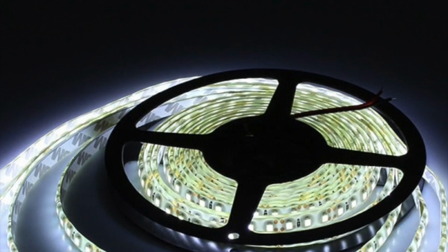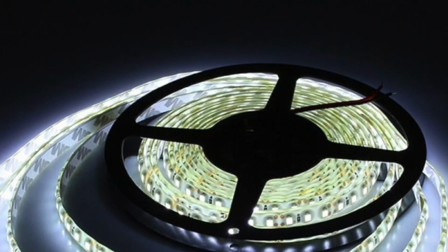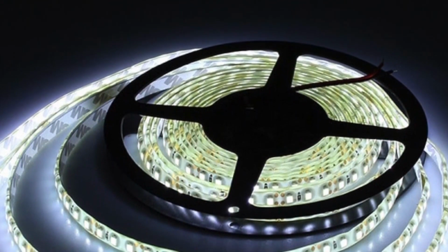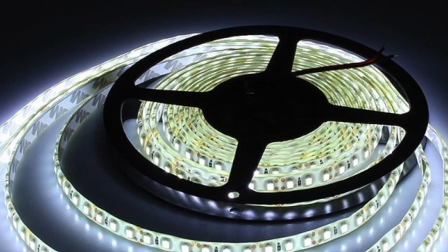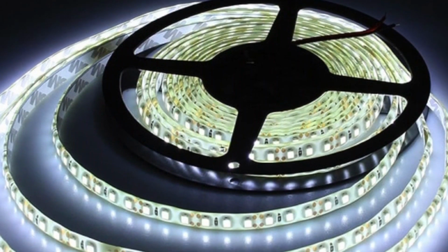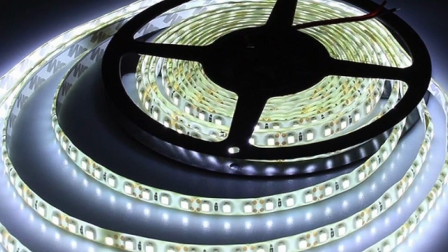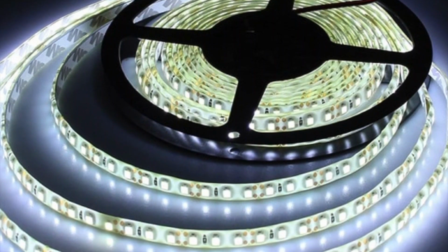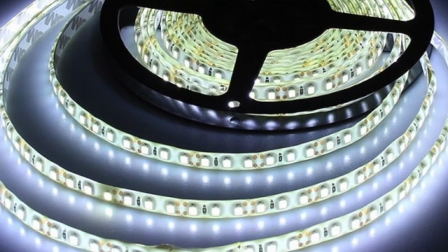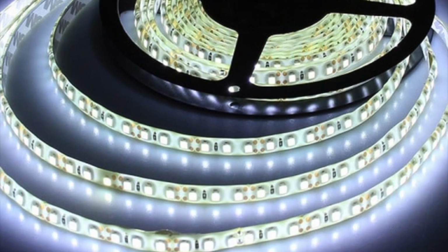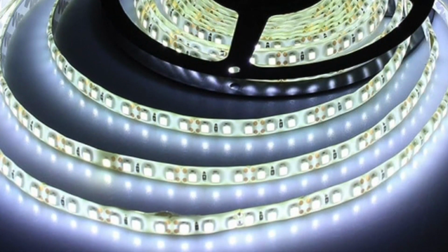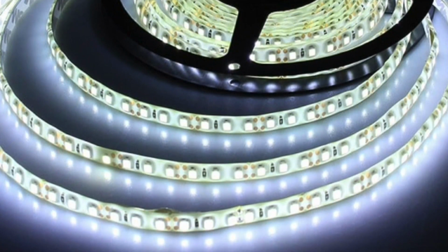However, it's safe to slightly over-amp your projects. Since amps represent the potential rate of flow, not absolute magnitude. Choosing a power supply that provides about 20% more than the max amperage you plan to use will help decrease heat at the power supply and support the longevity of your lights. It's a good idea to do the math to ensure that your power supply provides enough amps to light your lights at full white, too. Otherwise, you could toast your power supply at midnight right before you present your project. Ask me how I know.